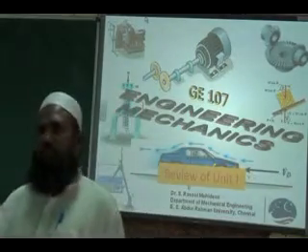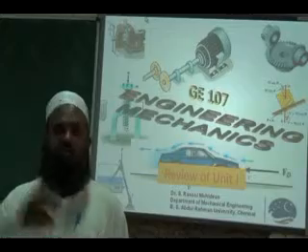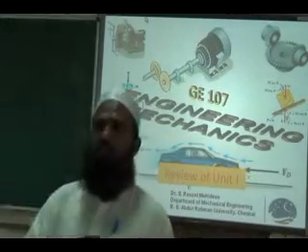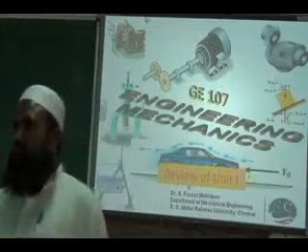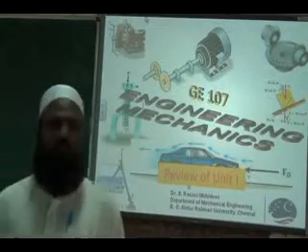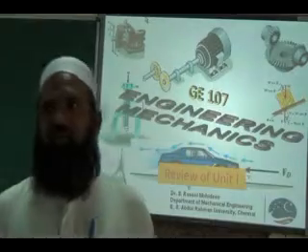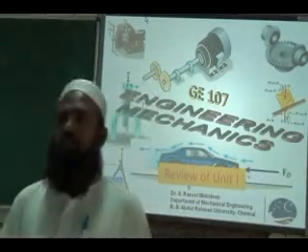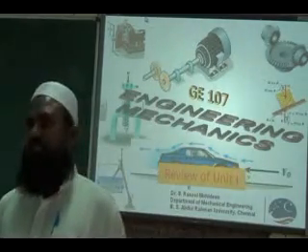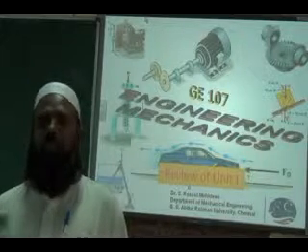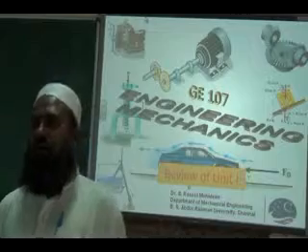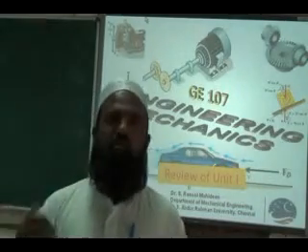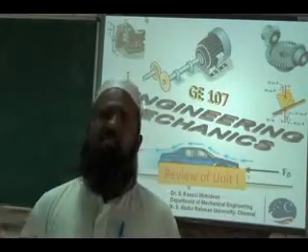We considered how to resolve a force into two components by using the parallelogram law and triangular law, sine rule and cosine rule, to get the numerical values of the resolved components. We need to resolve the forces in order to analyze a system of forces. In general, if many forces are acting on a body, in order to get the net effect of the forces, we have to resolve the forces along the axes which are easier for us.